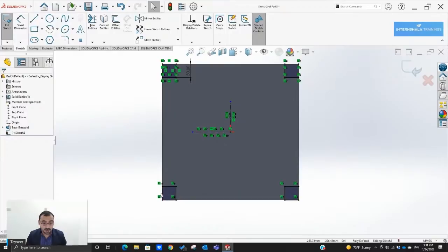And again, if you notice all those green symbols, all of those are different parameters that exist within our design. Now, let's say that maybe we got confused. The leg is not 50 millimeters, it's 40 millimeters. Well, it's fine. We can simply change that.